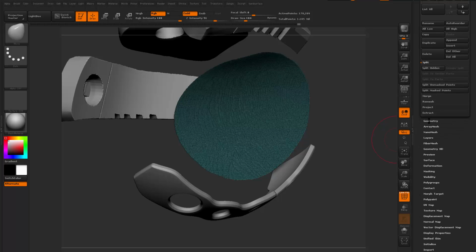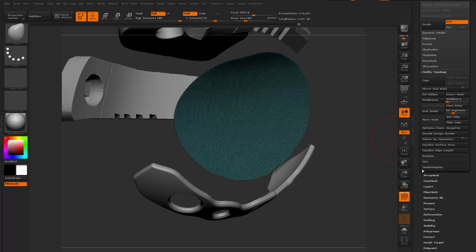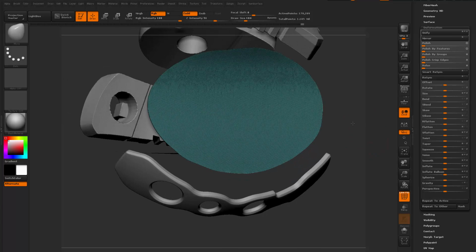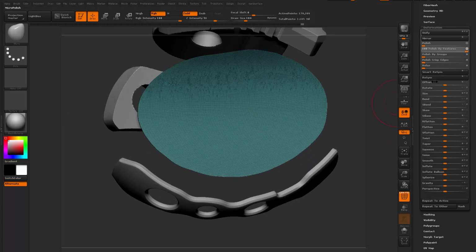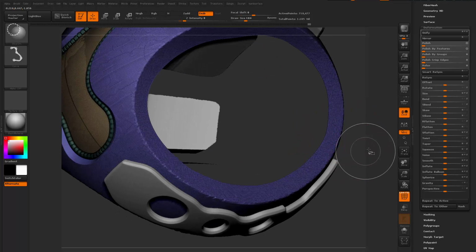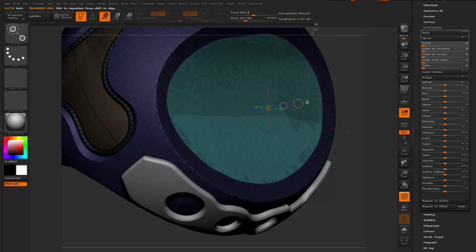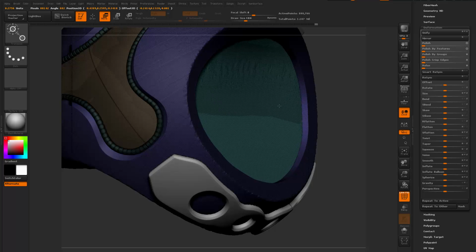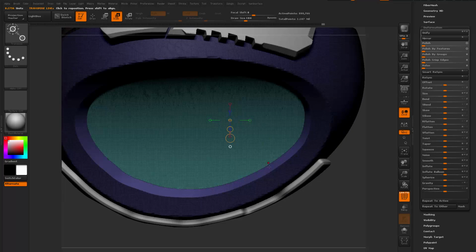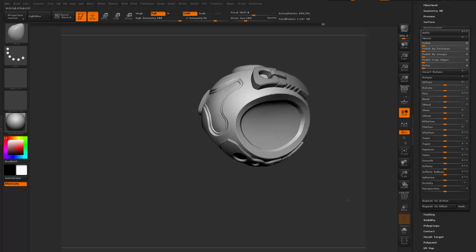The same trick I did earlier: geometry, then deformation, polish it again, and then isolate, Control Shift to push it in using the move, and then scale it to have some indentation. Alright, so that's dipping in now.